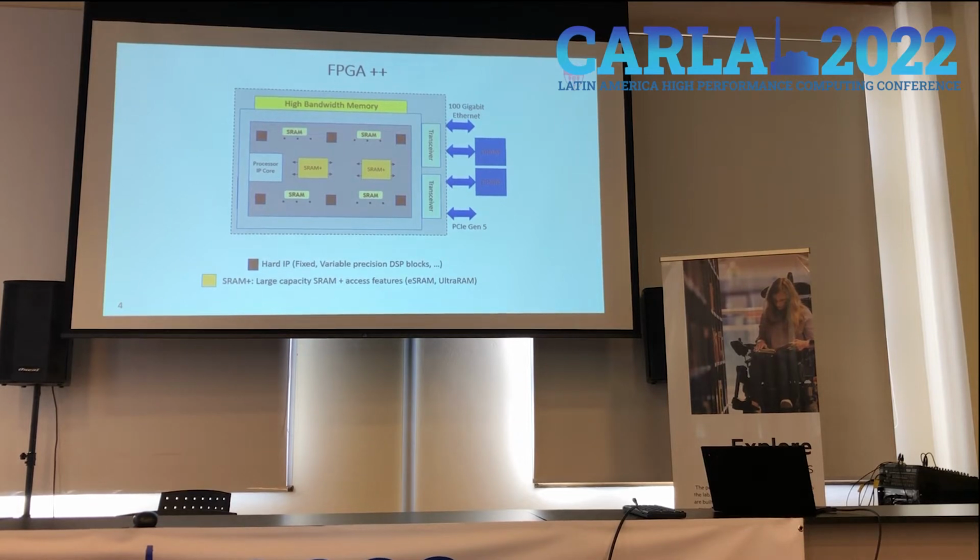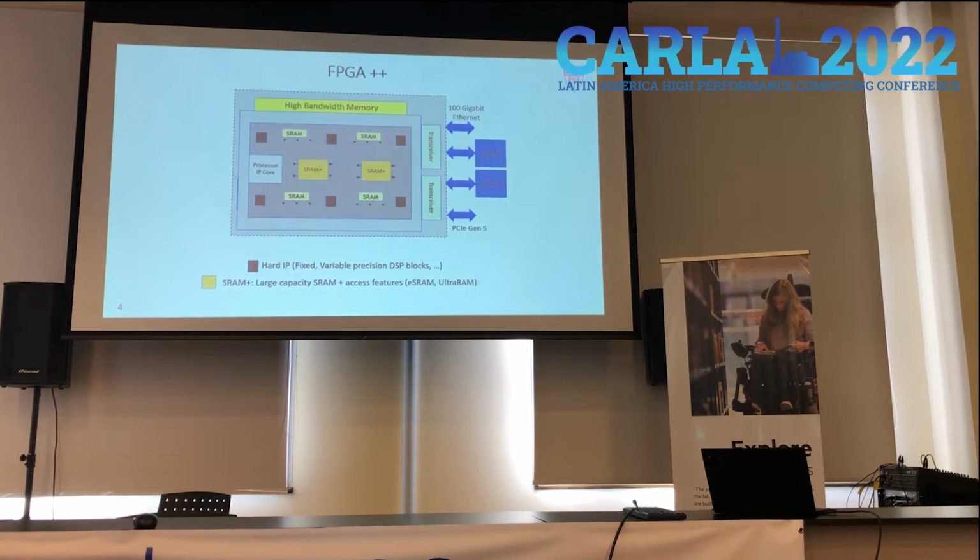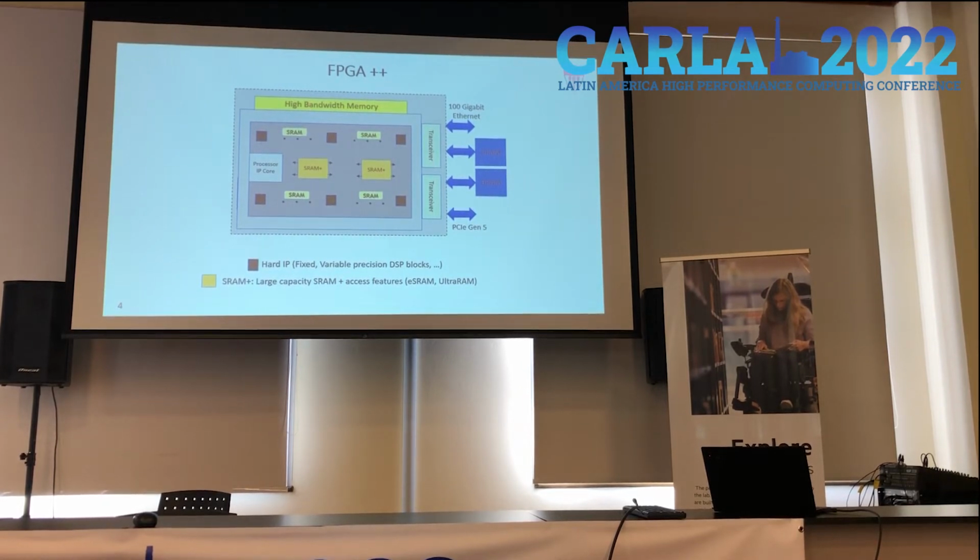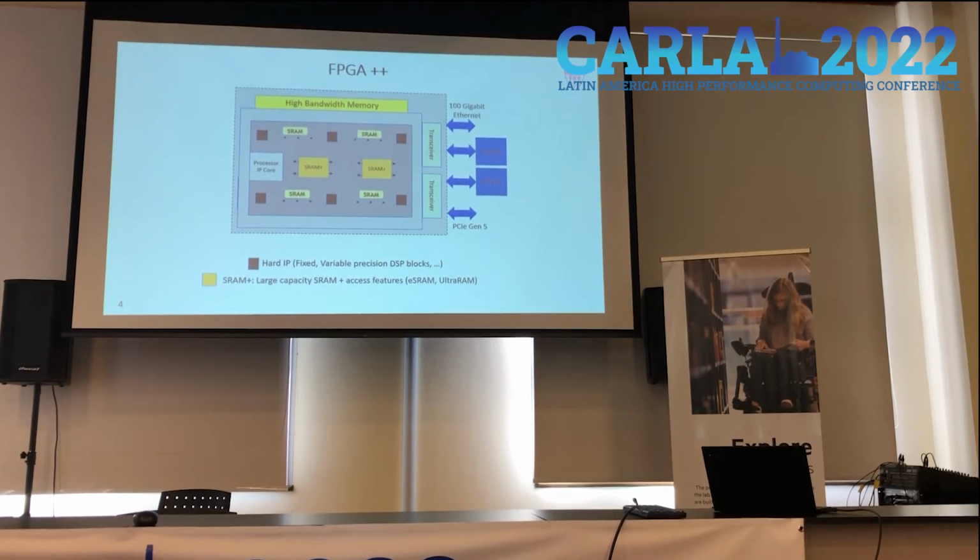There are almost 30 years of hardware research in this space, where these devices have significantly advanced. If you look at a modern device in the market today produced by AMD or Intel, they have quite a bit of on-chip resources, static RAMs, and also what is called hard IP integrated into these devices. You can get 16-bit multipliers, IEEE floating point multipliers, single precision multipliers, or variable precision arithmetic. Quite a bit of high bandwidth memory is available, just like in the GPU case. A number of external memory interfaces are available here. So these devices are quite powerful.